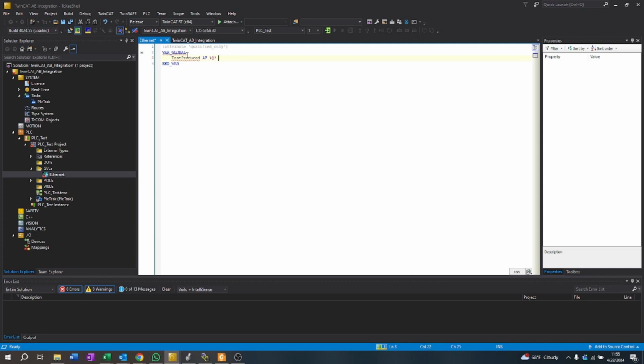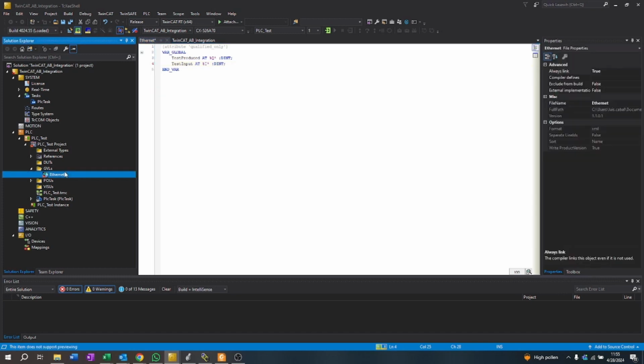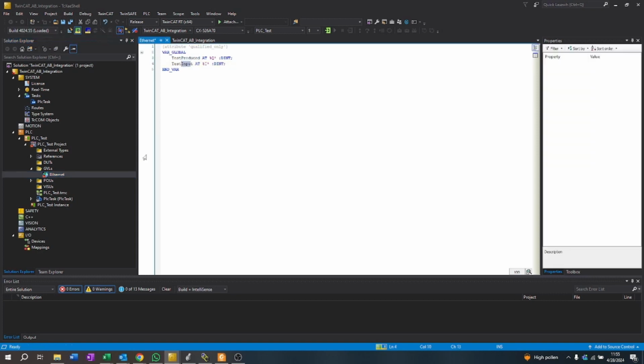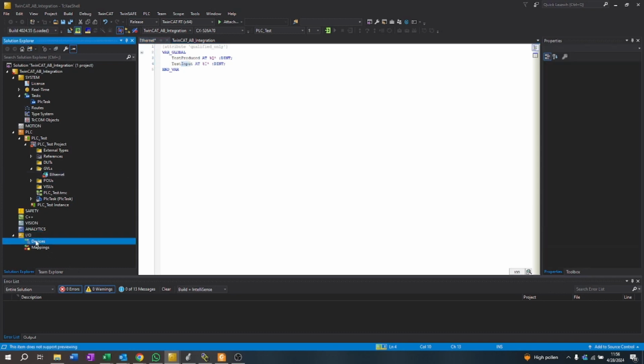And that's because we're gonna be, quote unquote, outputting it from our PLC, or IPC, I'm sorry. And then input, if you already have something built and you just want to communicate with, this is probably not your case, but I'm just going to show you how to do it. So I have created a produced tag that's going to be kind of like an alias if you're familiar with the Allen-Bradley world. So now that you have created that, let's go ahead and